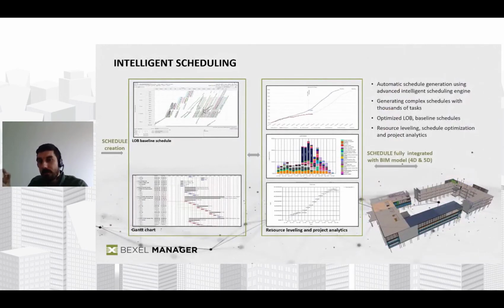And as a product of this process, at the end, the user gets a simple schedule structure. Why do I say schedule structure? Because the duration of all the tasks is equal. But there's no problem because the schedule structure is completely customizable. So the user can change everything in this newly added schedule structure. They can change and optimize durations, and change and fine-tune the relationships. The great thing is that you can also switch between line of balance view and Gantt chart view for the same schedule. So you can also optimize it regarding the line of balance and flow line.